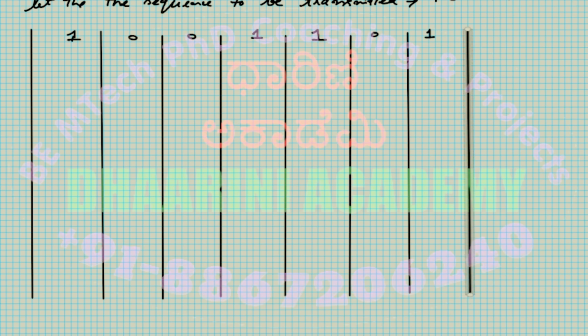Now just to differentiate data, I'll draw one line. So this corresponds to just simply the data. Now the first format which we are going to plot here, I'll write the name in red color just for your reference. This is NRZ, non-return to zero. NRZ stands for non-return to zero, and the name is called unipolar. It's a category of pulse, a specific type of pulse. Anyway, let me draw that.